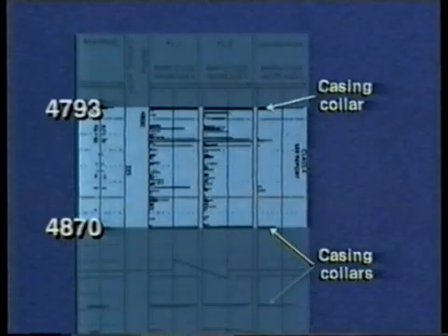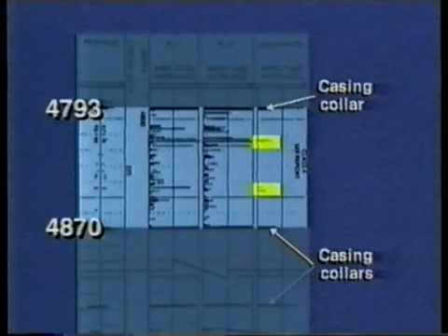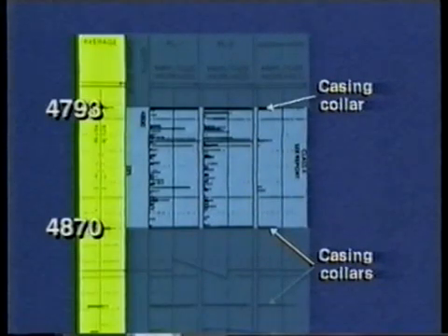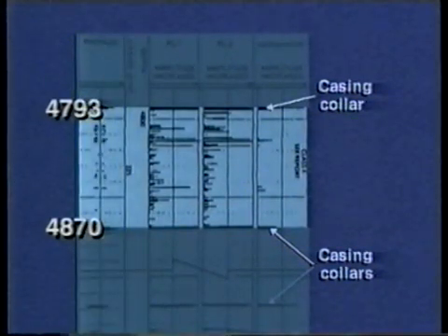In this example, the interval from 4,793 to 4,870 feet, 1,401 to 1,484 meters, shows general external corrosion, since the inner wall is clear of defects, except for the two intervals here. The track labeled average shows the average of all the FL1 and FL2 responses as seen by the pads. If the defect is large, it is detected by many or most of the pads and therefore shows a large average. A single point defect shows a small average reading.